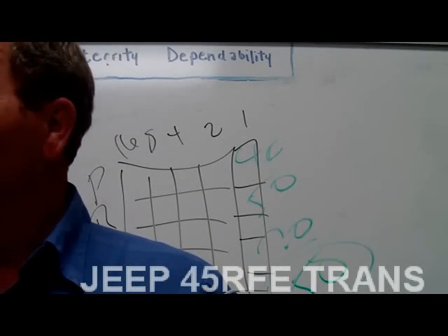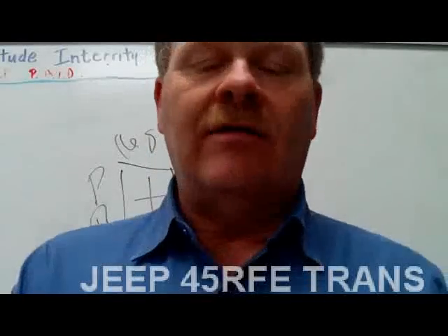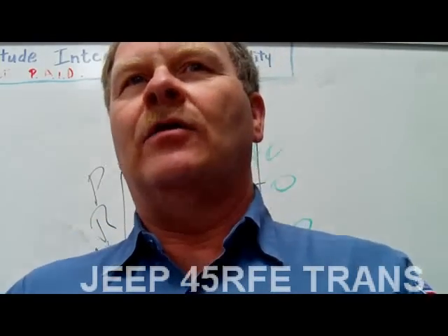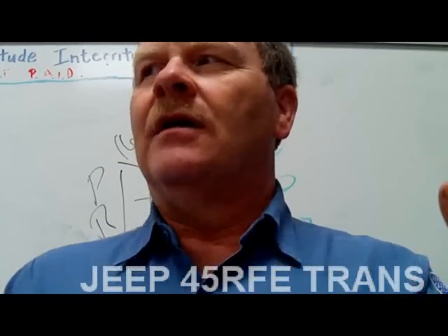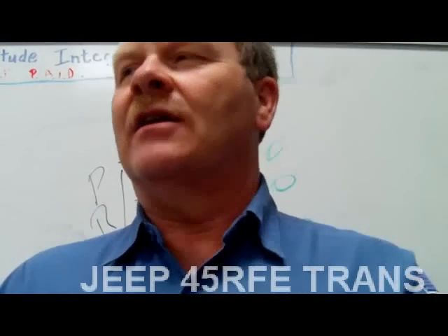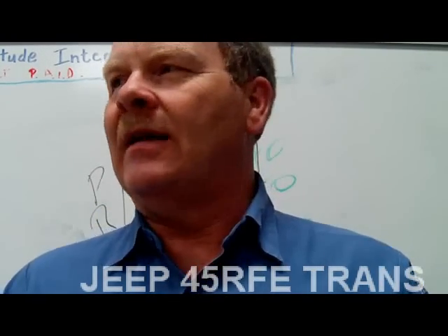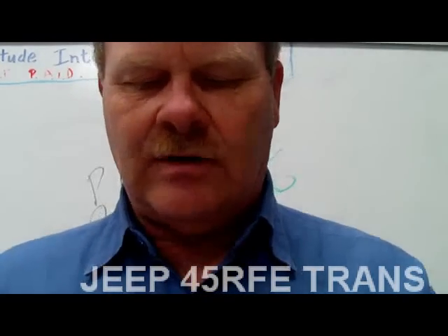You know what that means? What I was talking about a while ago. Grade hunting. It's not just when you're using cruise control, but anytime you're on a grade, going up and holding a steady throttle angle, it's looking at engine load, and it's going to take engine load into consideration when it decides whether or not to downshift and upshift. Because you don't want this thing hunting up and down through its gears. Whenever you're going up, it's just aggravating when it does that.